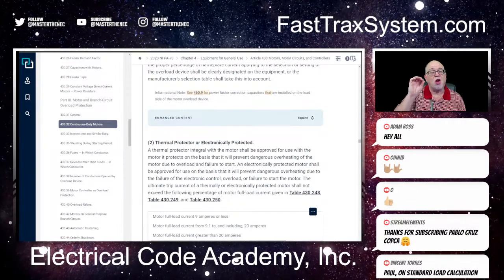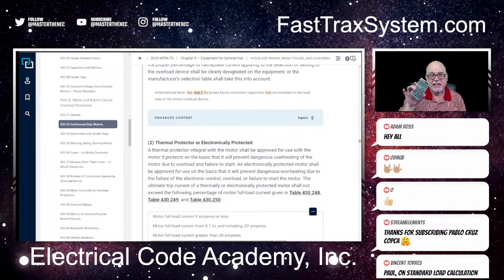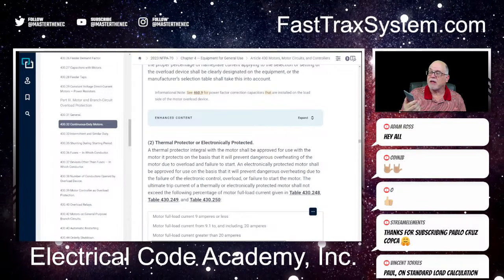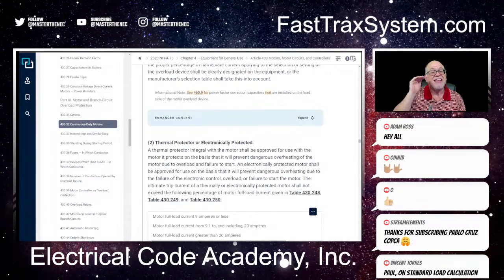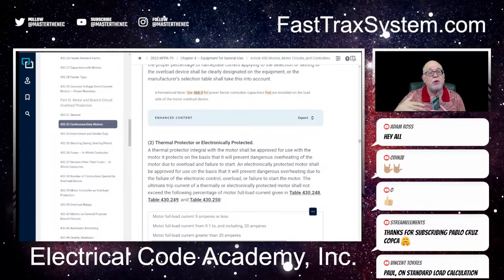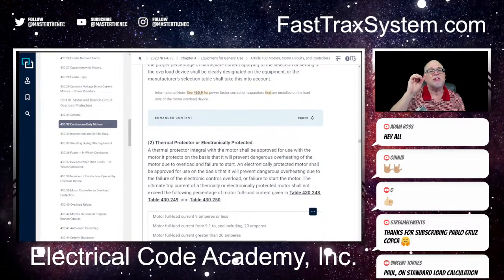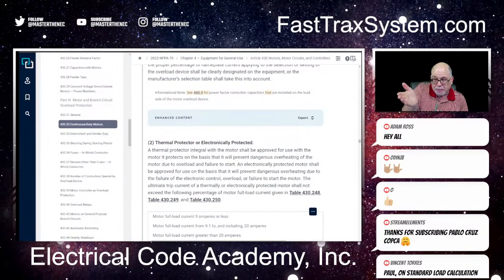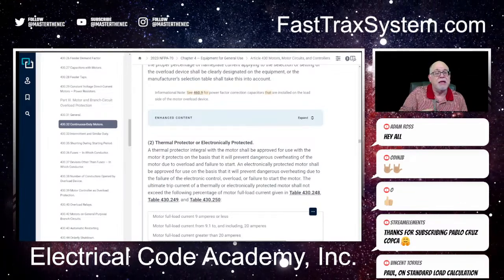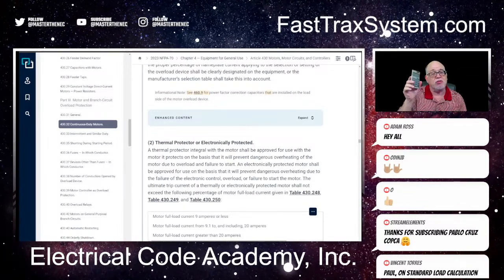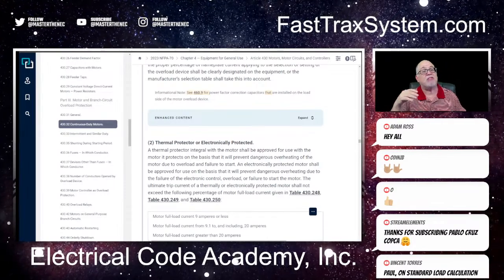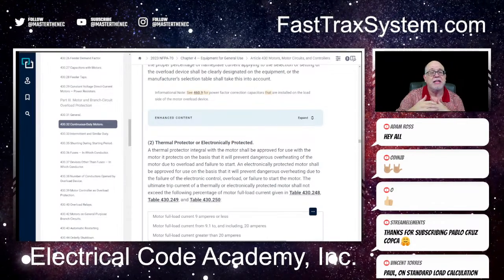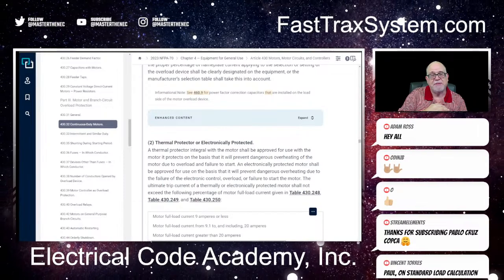So as long as it doesn't exceed 12, and a 50 ampere at 240 would be 12,000, that still would be under Column C, which if we did a load calculation would allow it to be 8 kW. So that's why I would take 8 kW. If they put in that range and it's a 50 amp, then I would just use 8 kW for that, because that's what our demand allows for us in 220.55.